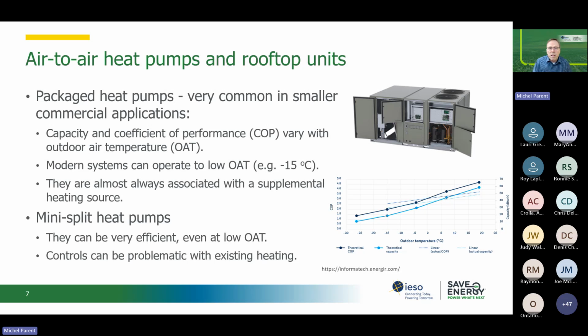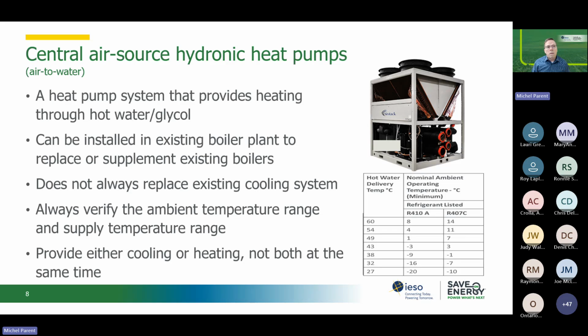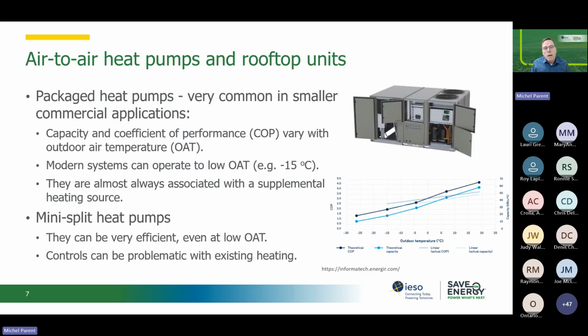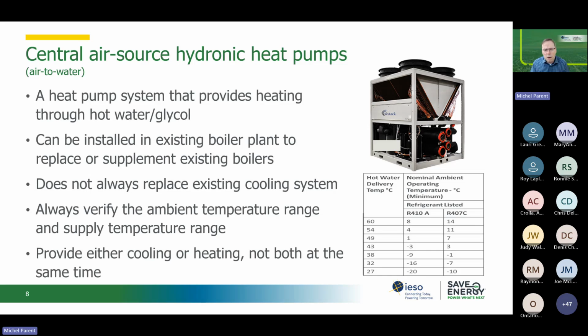Mini split heat pumps are very similar, but obviously they're split, and they usually don't have integrated supplemental heating, whereas the air-to-air rooftop unit will have integrated supplemental heating. And we're going to talk about the importance of integrating that control into your BAS rather than just using the onboard controller. That's where the integration part will provide you more benefit than if you try to use only the onboard OEM controller for those types of heat pumps.